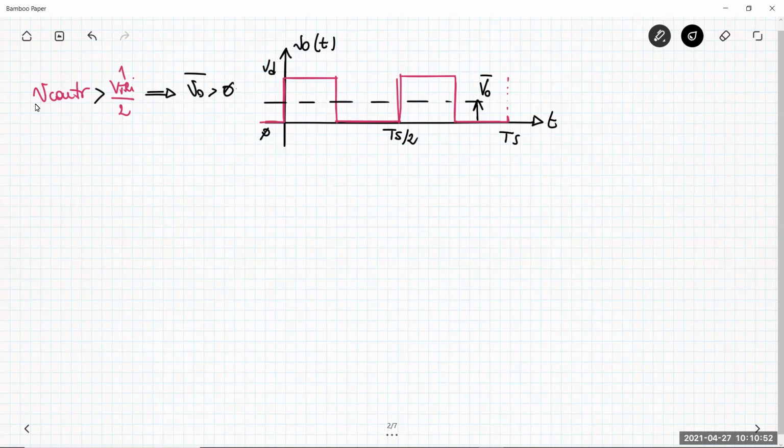What happens in the first interval, in which V0 is equal to Vd, is that you have, for example, TA plus and TB minus that are on. We also learned that there is a difference between devices that are commanded to be on or off, so commanded to be closed or open circuit, and the device that conducts the current.